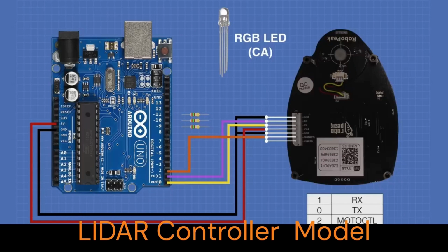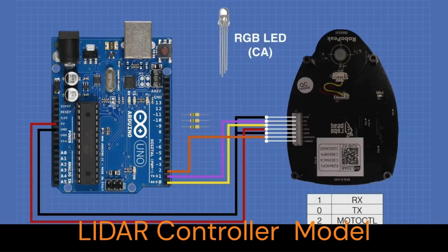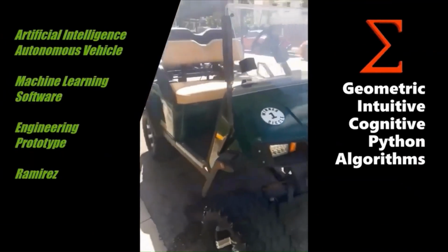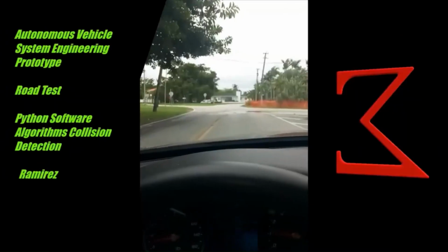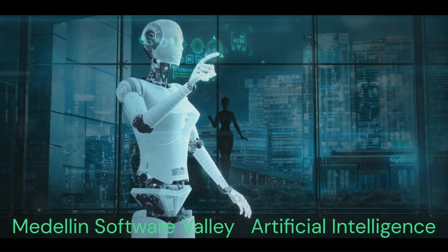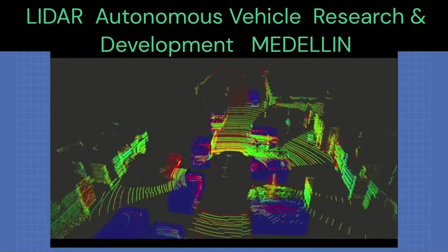Now, we can apply continuous wave LIDAR, which is different from the pulse LIDAR. It uses either amplitude modulation or frequency modulation of the light source. An amplitude modulated continuous wave LIDAR system typically operates at a wavelength of 905, 1300, or 1550 nanometers.